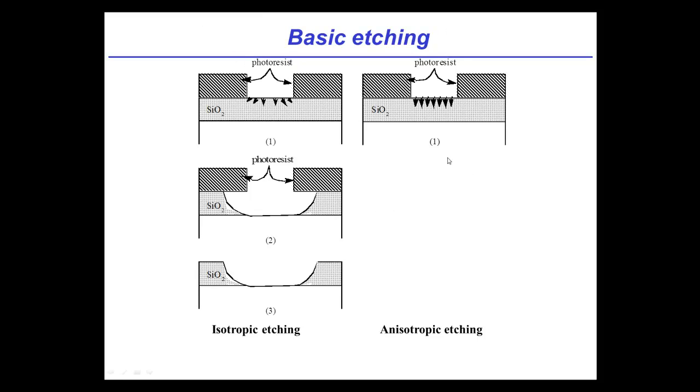That's probably true, actually. Okay, so let's look at another one, anisotropic etching. Anisotropic etching, as the name implies, will not be the same in all directions. So there's going to be some direction in which the etchant works preferentially. We're going to start with the same example: SiO2, or silicon dioxide, with a mask of photoresist. But this time when I add the etchant, it's not going to eat evenly in all directions.